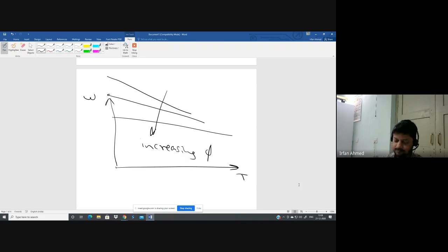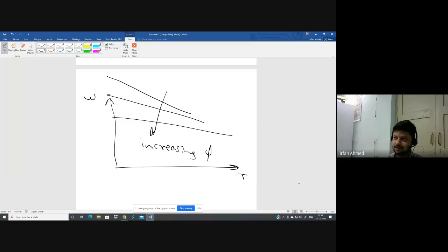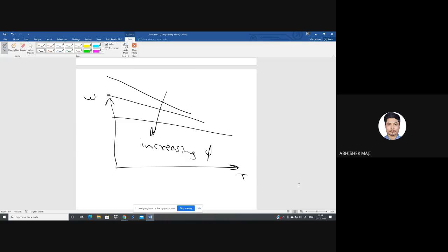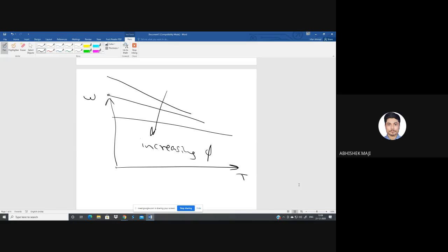Yes, anyone else? So negative of the residual flux. It means we are saying negative flux. How can you get negative flux? I mean, we can decrease up to 0 and still there will be residual flux. And if we decrease further in the opposite direction, then the residual flux will also decrease. So the motor will not start.